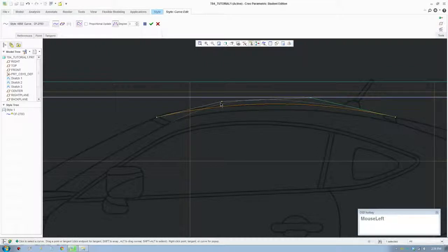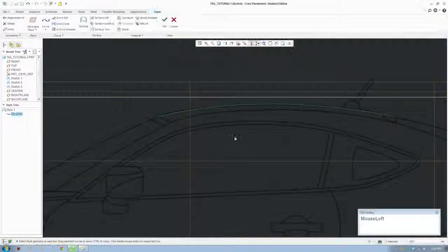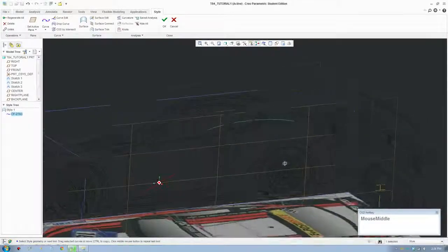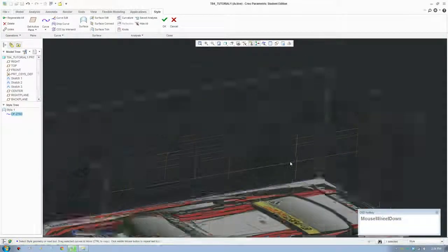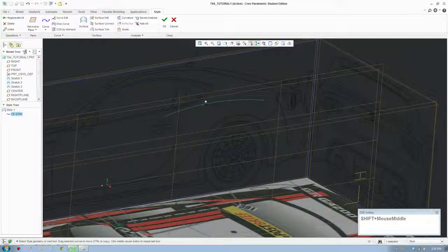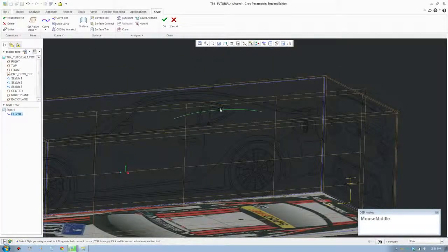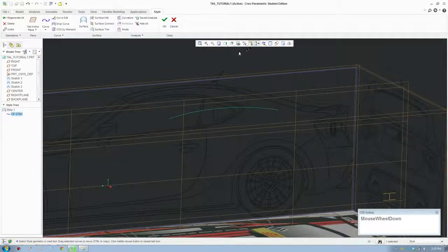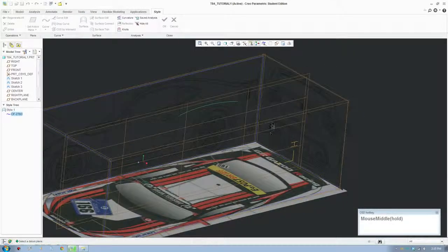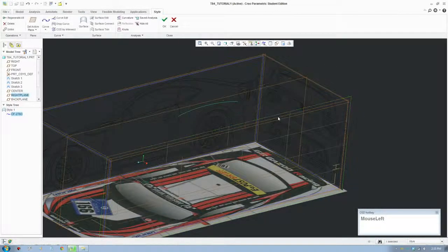So when you draw your curves, make sure it's basic and simple. Use the minimal number of points as you can. When you build a car surface, it's like using plywood. The surface can't be bent too much. You don't want to put a lot of points or a lot of bends on it, or it won't look nice. Yeah, imagine you're trying to build a car with plywood.